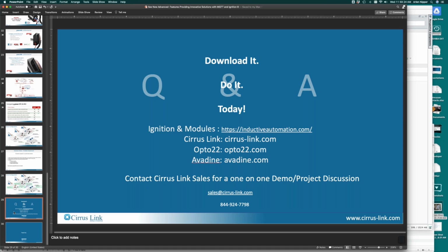Cool. Good. This one I think is for you, Ben. What about the approvals and compliance ratings on the Groov Rio? Yeah, great question, because we've got a lot of this stuff out in some pretty harsh environments, and it's obviously important. So temperature is minus 20 C to plus 70 C. And we've got the whole suite of agency approvals. We've got UL, Class 1 Div 2, CE, ATEX, and a few others there. So there's a nice Groov Rio data sheet available on our website. So just hit up opto22.com and you can pull that down.